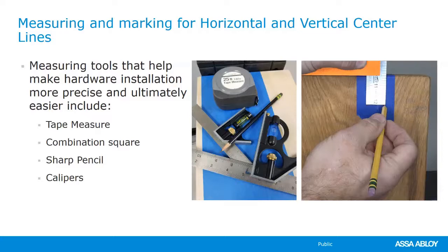And I've never been very good about just drilling through the door and it being perfectly on the other side. And I don't know very many people that are. So I always drill halfway through the door on one side, halfway through the door on the other, to ensure I have an accurate install.